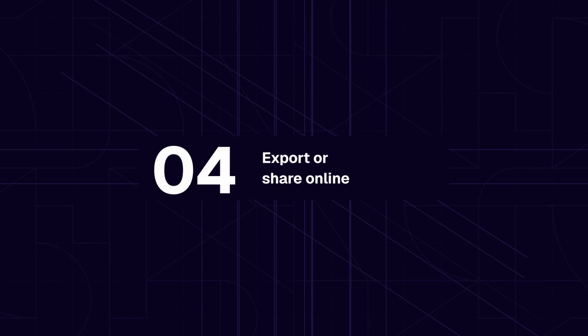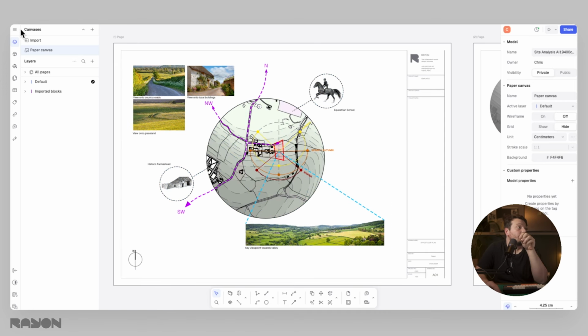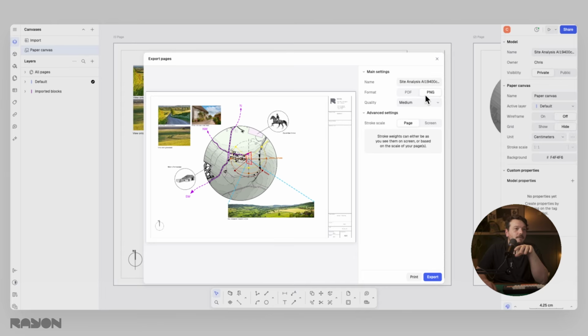With the layout completed, we can now export our presentation. With our sheets finalized, we can do a couple of things. So I can export them as images. So if we just go to export, I'll go to images and I can choose a page. And I would just export that as a PNG. So I can change the file name, I can change the quality, so low, medium, high, and that would just export as a single image.